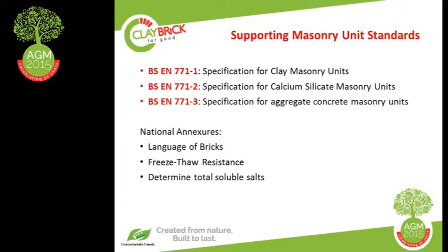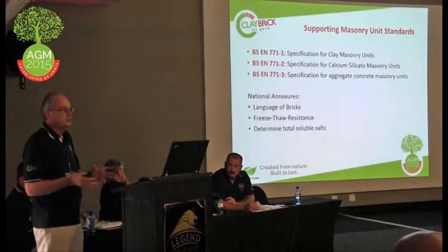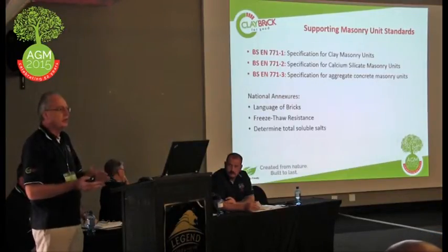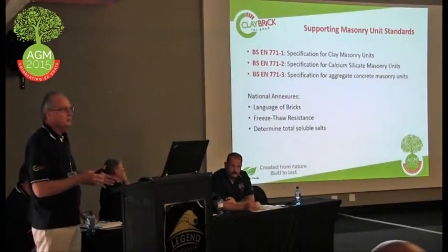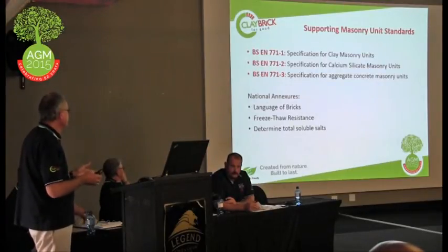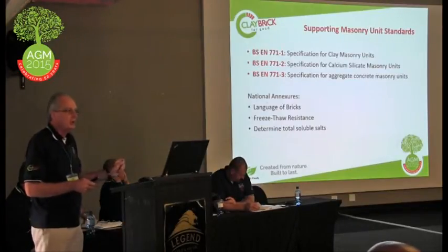And for instance, the language of bricks, which we have got, which is NFP, NFX, FBX, FBA, that I would recommend we would keep. It's a good marketing tool. The architects do rely upon it. That would then be put into the national annexure. Now, the British standard or European norm standard clearly has requirements and test methods for freeze-thaw resistance. That we would just, in the national annexure, say not applicable to South African conditions.